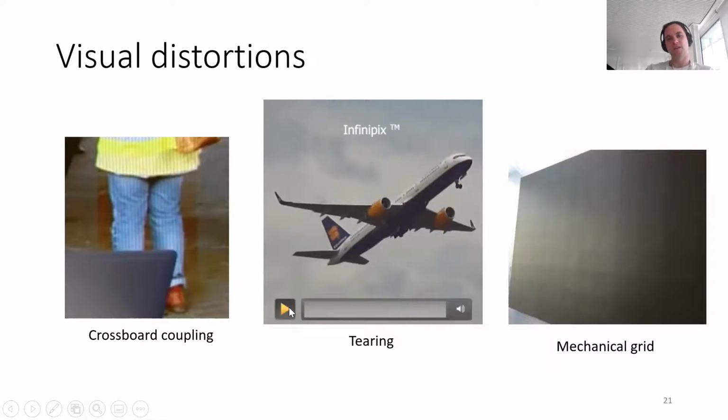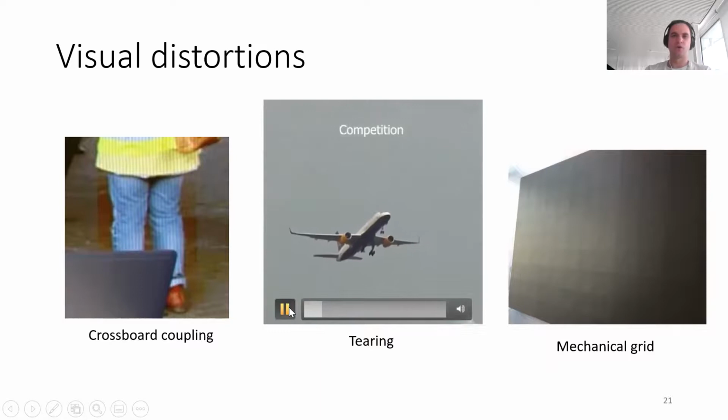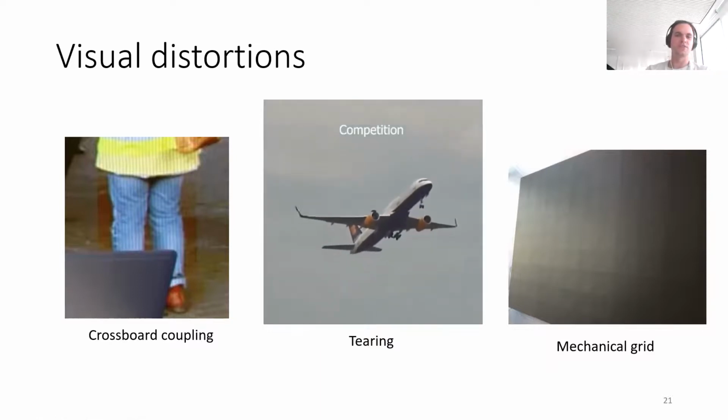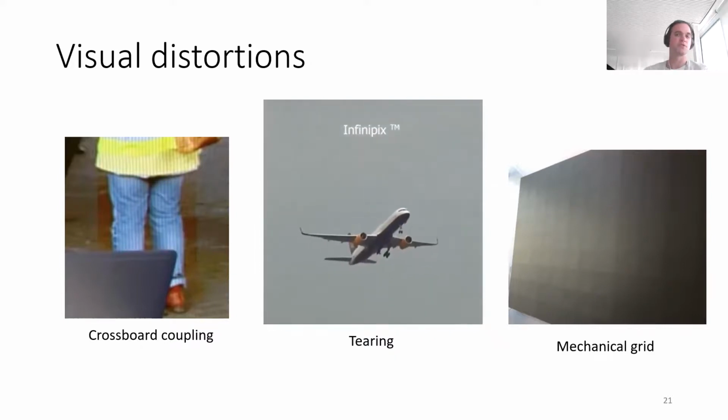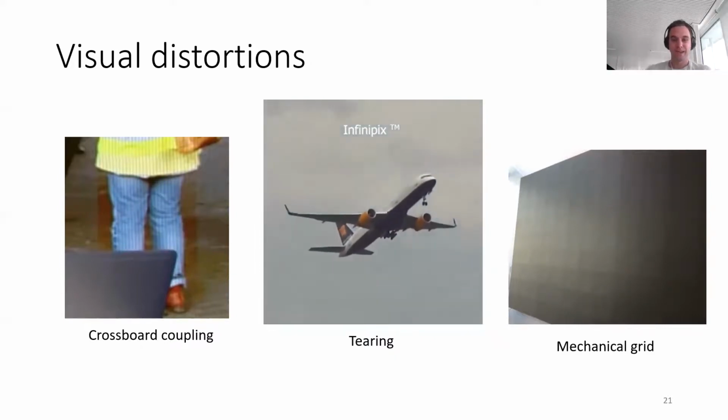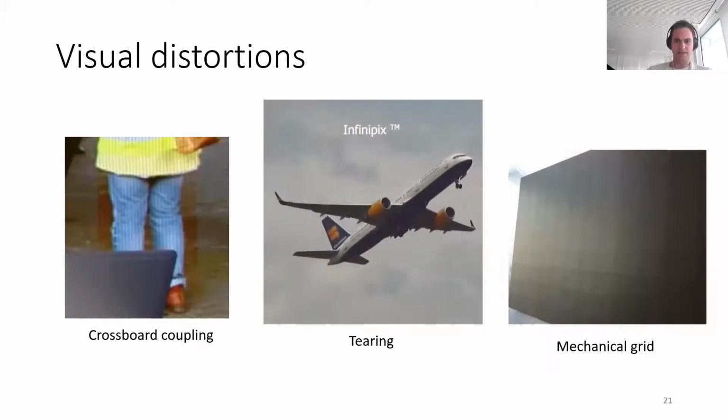The next one is an example of tearing, which can occur in between two sections of the display which are driven by different image processors. LED is a modular system, so we can easily exceed the capacity of one processor. So it's very important that the different processors work well together. And of course, with Infinipix, which is the controller driving all Barco LED products, we have that perfectly well under control using fixed delay.